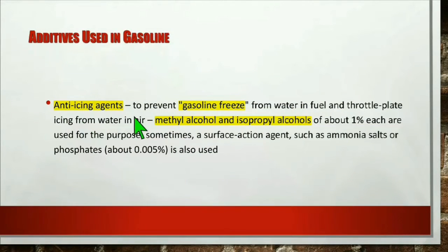Anti-icing agents to prevent gasoline freeze from water in fuel and throttle plate icing from water in air, methyl alcohol and isopropyl alcohols of about 1% each are used for the purpose. Sometimes, a surface action agent such as ammonia, salts, or phosphates about 0.005% is also used.